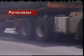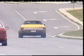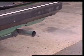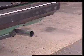This section examines particulates. Particulates from modern engines are usually carbon-based. Older vehicles may produce lead-based particulates. This is caused by lead compounds used in the fuel to raise its octane rating. In spark ignition engines, particulates are caused by incomplete combustion of rich air-fuel mixtures. In compression ignition engines, they are caused by a lack of turbulence and lack of oxygen.